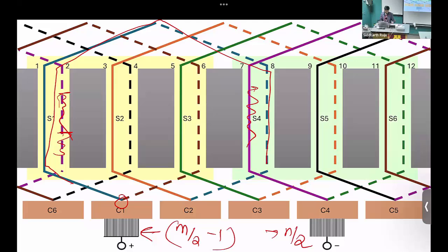In a DC motor, typically it's very hard to get a configuration where you can get a single layer winding. And people usually don't do it either because there are a lot of advantages that you gain by doing a double layer, including mechanical stability as the rotor starts to rotate. But when we go to AC motors, we will see single layer windings there.